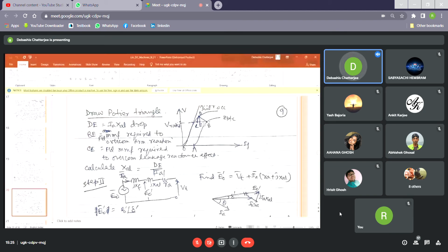Another thing which I told while drawing the OCC: the OCC has quite a bit of linear portion, due to the air gap present in the magnetic circuit. If you draw a line tangent to this linear portion, you get a line known as the air gap line. Now from point B, you can cut section BC equal to OA.